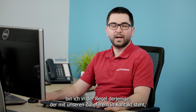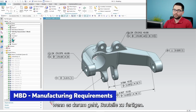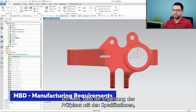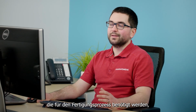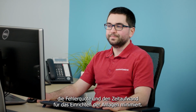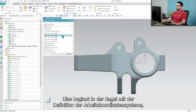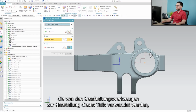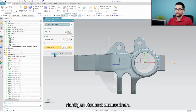Based on my experience with different manufacturing processes, I'm usually the one in contact with our suppliers when it's time to manufacture parts. I know that complementing the control plan with the specifications needed to feed the manufacturing process minimizes errors and the time it takes to set up the equipment. This usually starts with the definition of work coordinate systems that will be used by the machining tool to fabricate this part, which is typically required to associate the characteristics to the proper context.